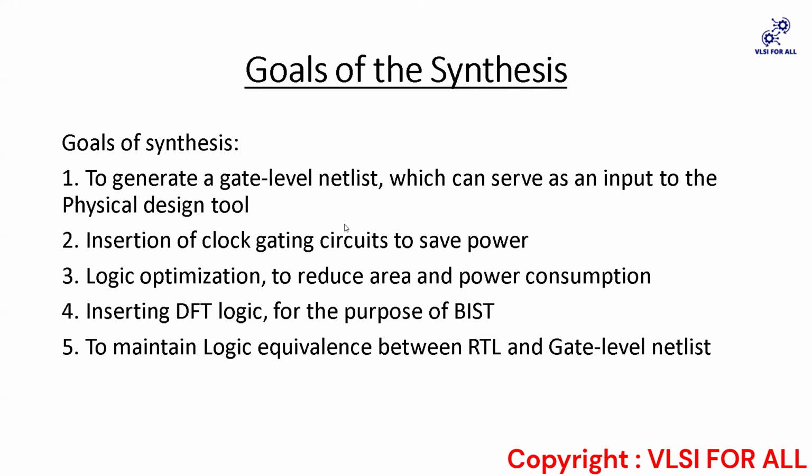So now after this, our other goal is logical optimization. We need to reduce the area and, of course, the power consumption. This can be done using the compile command. I'll get to that later. And also using constraints, we can optimize it.